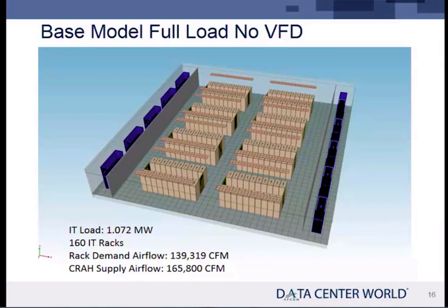So here's my data center. This is a fairly simple design. You've got the air handlers here behind the wall. This is very common to have the air handlers over here. They're in blue. And then the racks sitting here in a hot aisle, cold aisle configuration. The cold is in the center, and the arrows indicate airflow direction through the racks. These at the top are ceiling grills. There are end caps on the rack rows.